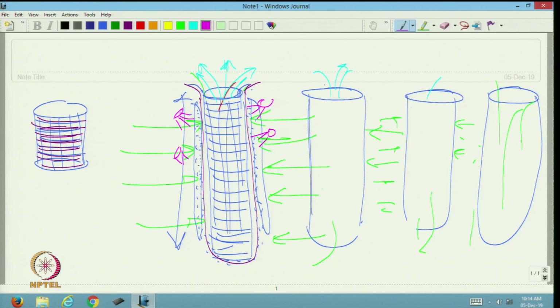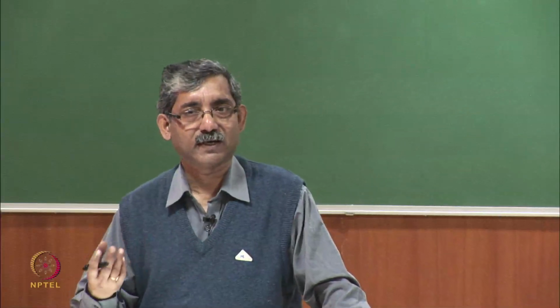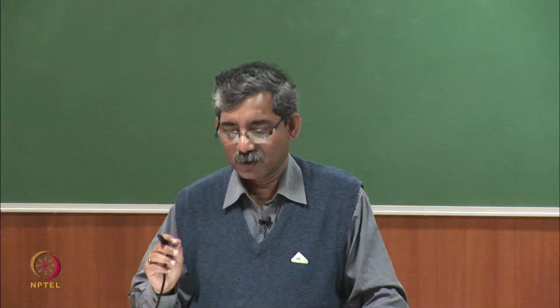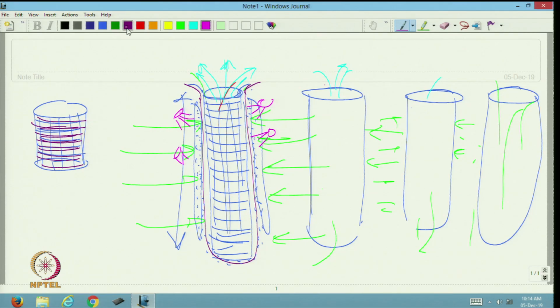Very high pressure air is injected for a very small span of time, say 1 second, 2 seconds, which will actually shake this filter media, and the dust cakes formed on the surface of this filter get released and will be collected at this point.